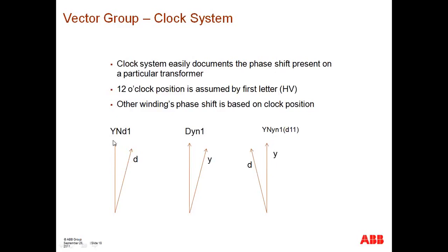So again, the capital letter Y represents the 12 o'clock position. The lowercase letter represents the low voltage winding connection, and the number that follows the lowercase letter signifies the position of that particular winding in relationship to the 12 o'clock position.